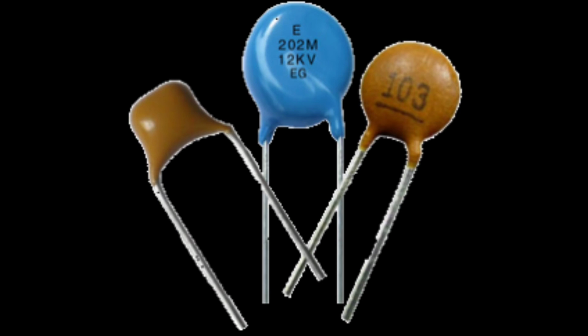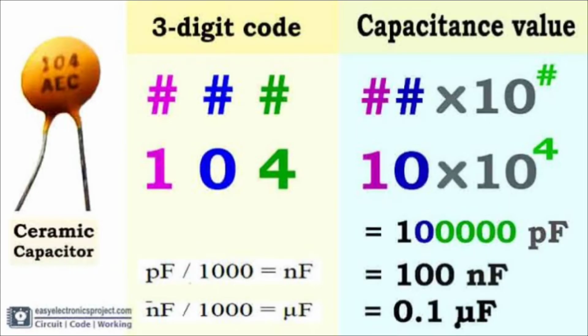Ceramic capacitor. It is made up of two layers of metal, usually nickel and copper, with a ceramic, paraelectric or ferroelectric as a dielectric. These alternating layers are stacked together to provide high capacitance value. The minimum thickness of ceramic dielectric layer is about 0.5 micrometer, and the voltage rating of the capacitor depends on its dielectric strength. These types of capacitors are used in resonant circuits, coupling, decoupling, and bypass applications.